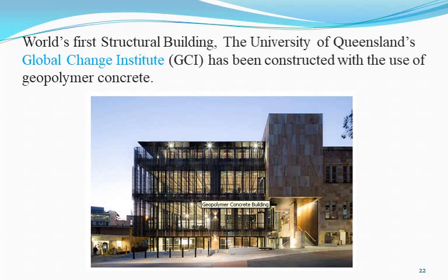Finally, we conclude that geopolymer concrete is a concrete made without using Portland cement, and as such, it is an environmentally friendly and energy efficient construction material with enormous potential in many infrastructural applications. The limited trial results show that geopolymer concrete undergoes very little drying shrinkage and moderately low creep, and possesses excellent resistance to sulfate attack.